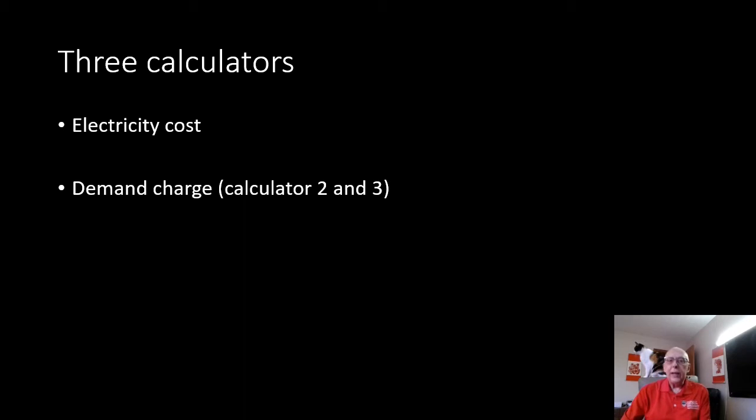But the bottom line is that as a commercial customer, your utility company charges you an extra fee, and this fee can be high, that is based on the peak power use during a 15-minute period during any billing cycle. So they basically look at the period of time that you use the most power, and based on that power use, you have a demand charge, or it may be called something different, but it is an important part of your electricity bill.